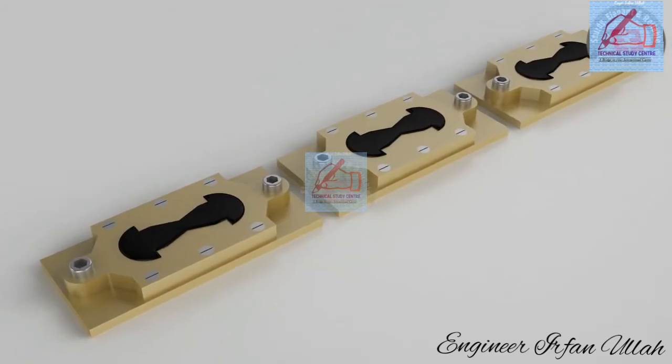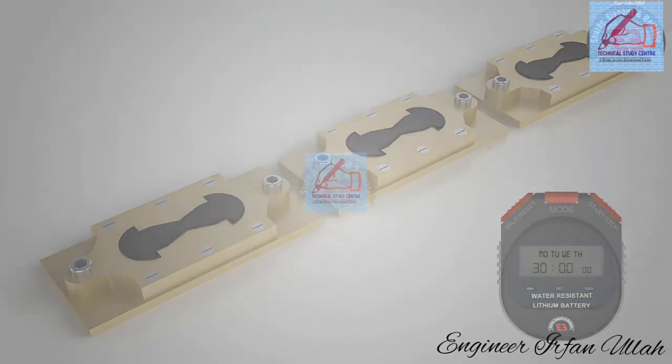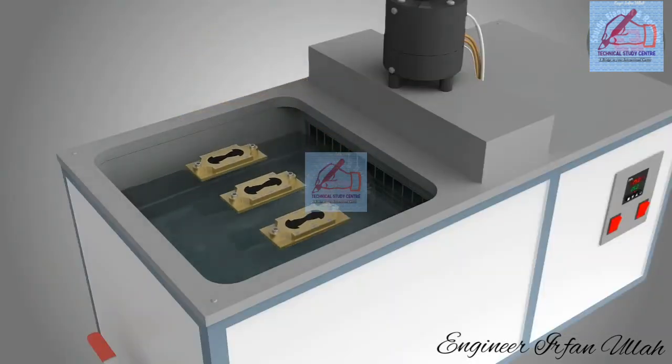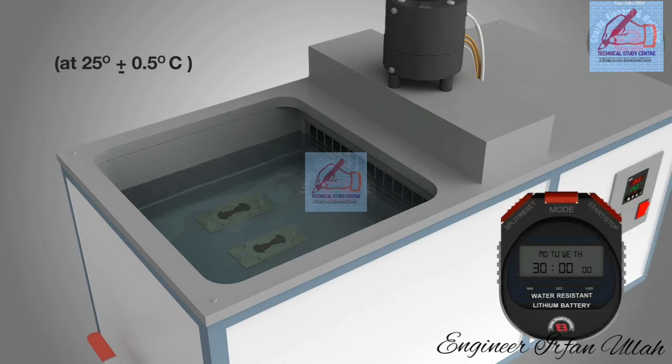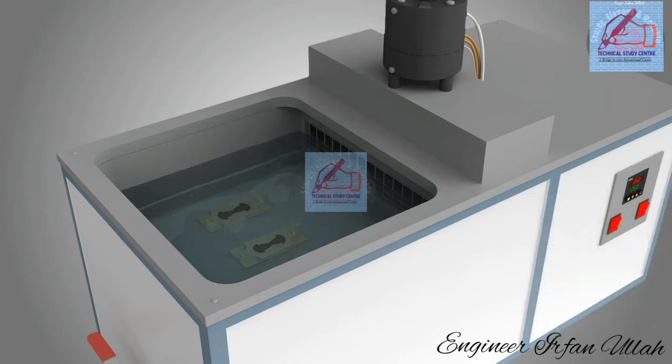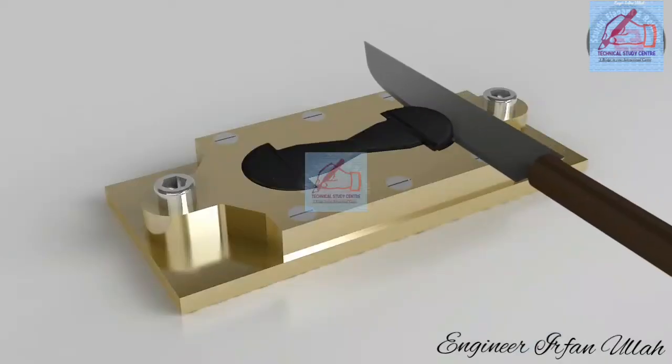The molds along with the plate assembly and bitumen sample are kept at room temperature for 30 to 40 minutes. The air-cooled specimen is then kept in a water bath maintained at 25 degrees Celsius plus or minus 0.5 degrees Celsius for 30 minutes. Thereafter, the sample and mold assembly are removed from the water bath and excess bitumen is cut off by a hot knife.